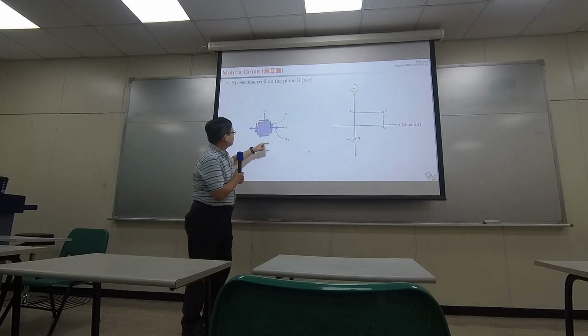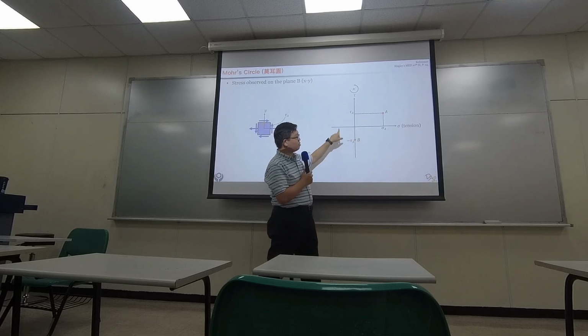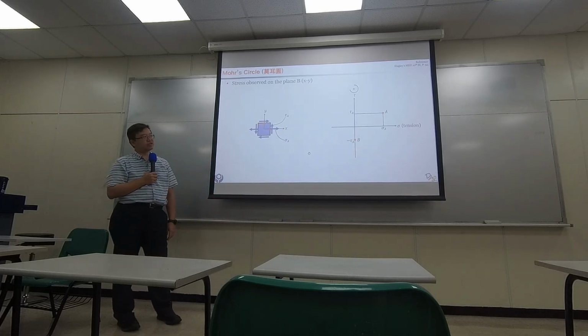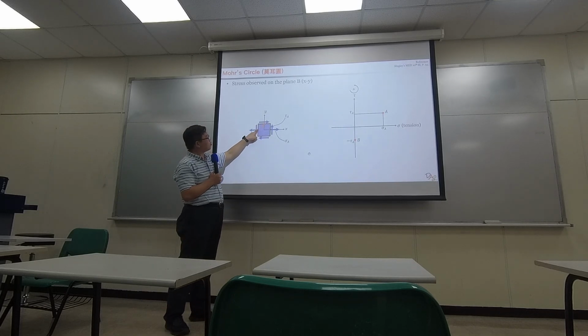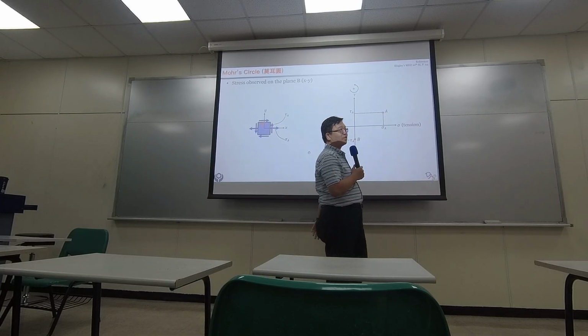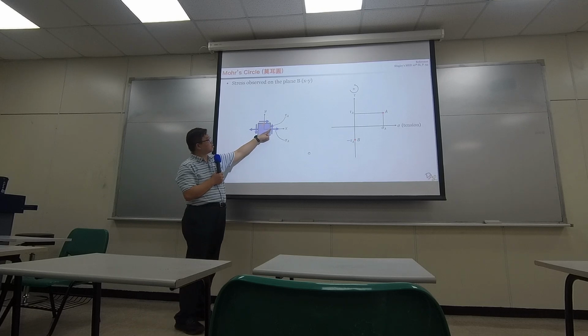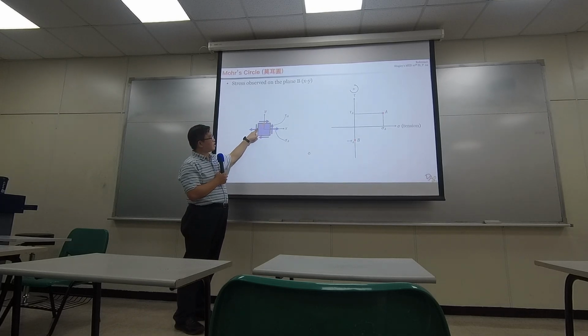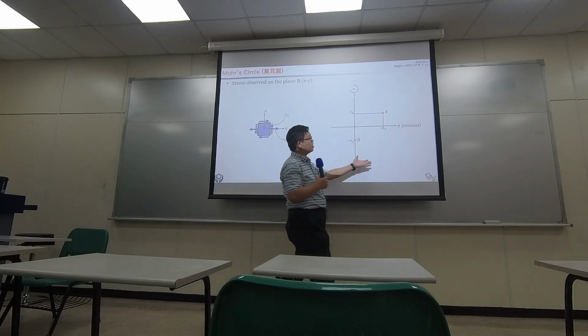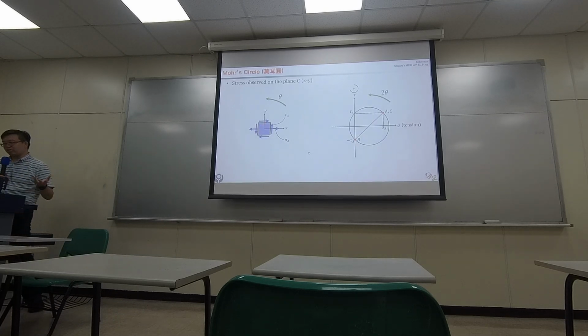So then you realize if you make a 90-degree turn in the real world, in the Mohr circle coordinate, you already made a 180-degree turn. Okay, so when you move to the opposite side from the starting point to the left, you already turned 180 degrees in the real world, but in the Mohr circle, you already turned 360 degrees. Okay, that's why usually for Mohr circle, you only need to investigate 2 points. You don't need to investigate the other 2 because they will be the same point in the Mohr circle diagram.